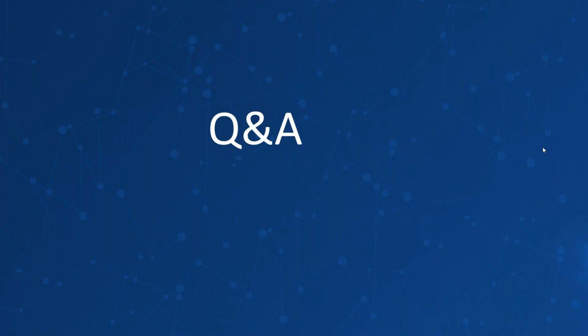A question for you, I will highlight somewhere that is probably important. We can take this. If some teams are not using Revit, we can't use design collaboration. What is the recommendation or easier process to use clash detection between several different teams' 3D models through BIM 360 design and docs? Yeah, so the BIM 360 Coordinate entitlement is a separate one. And what it can do is clashing between Revit files and IFC files that are exported out of certain authoring tools. So that's possible.